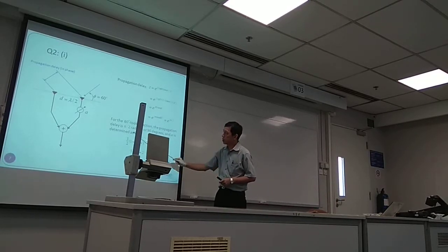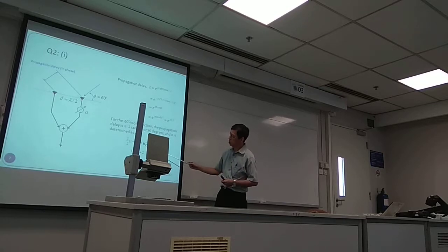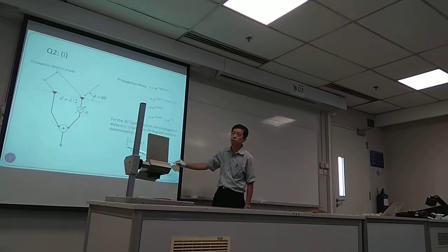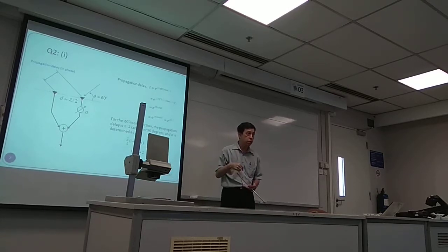we have the array factor or the general array response to be 1 over 2, 1 plus a z. So this is basically the polynomial of your array factor. So we have 1 over N, the big N, and in this case, N is the number of elements, 2. That's why 1 half. And 1 plus a z. So a here is to be determined.